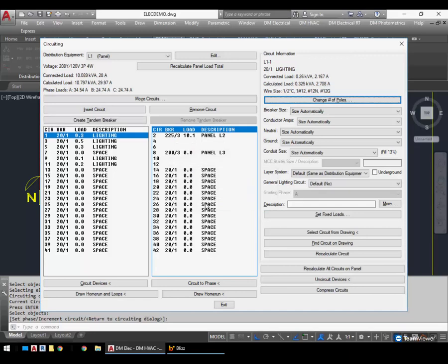That's the functionality that we're trying to handle there: the NEC requires that if you're combining circuits and you're combining the neutral in the home run, you need to have a common trip, and so this is how you handle that with our software. You don't want to just combine them. You actually have to have a common breaker for them so that if one trips, they all trip together. So that's changing number of poles.